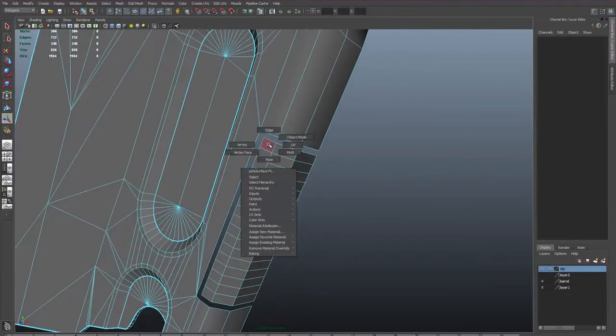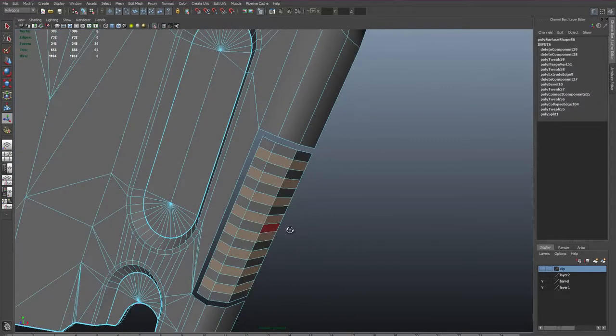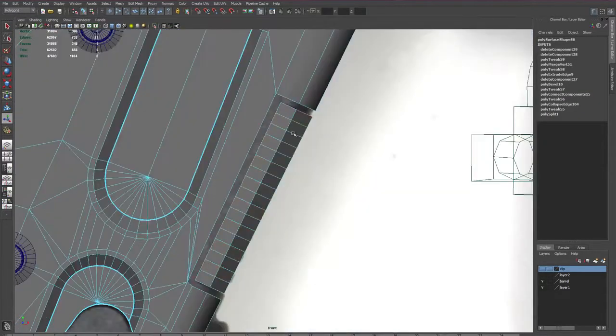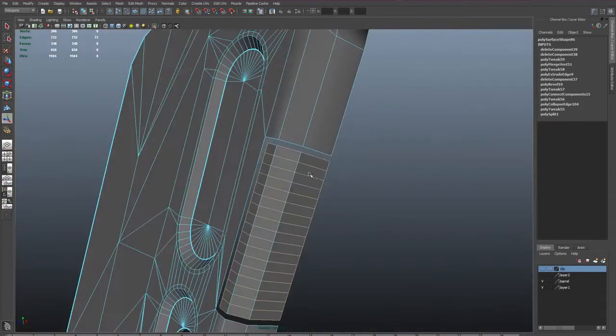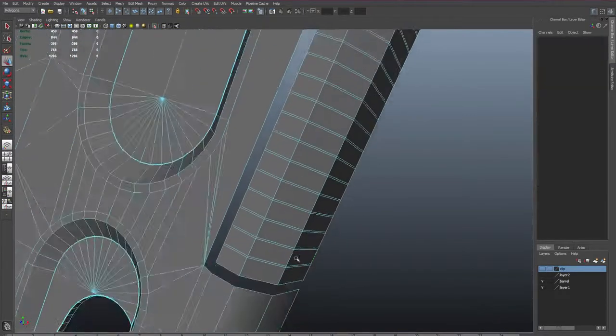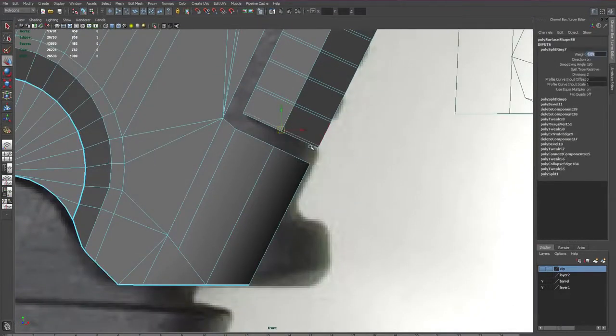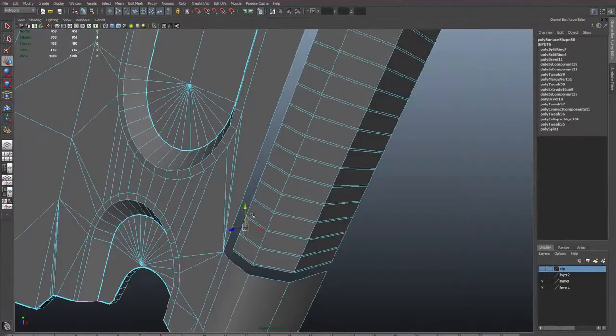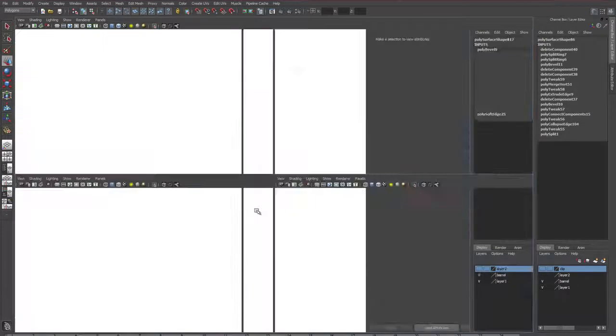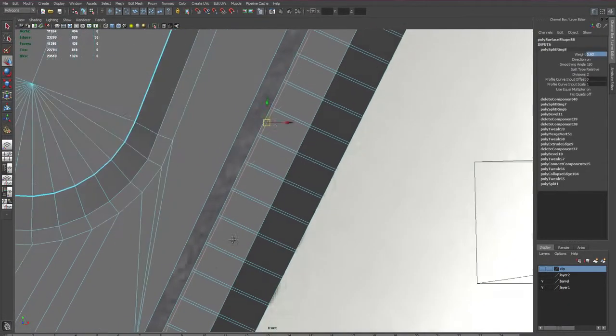And I delete the border around the grip object. This will isolate the detail in this area so that it won't continue back into the main body and complicate things. And instead of extruding, I'll bevel the edges to create the horizontal rows that I want. This will make things easier because it'll save me from having to bevel the final result.